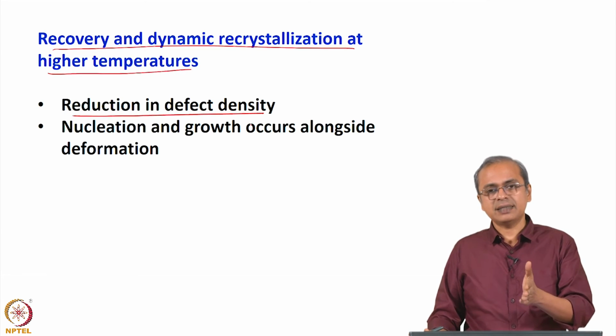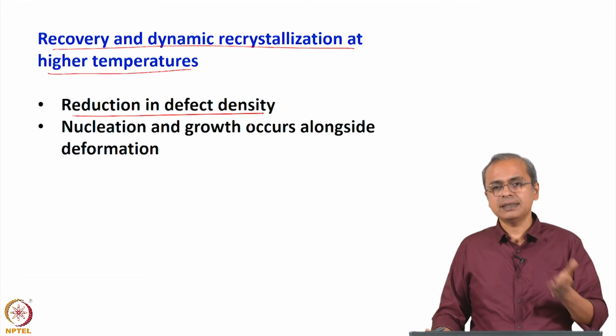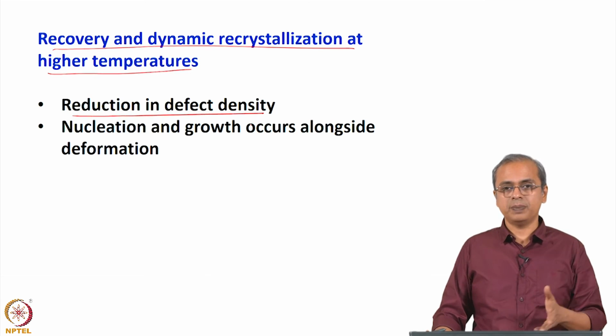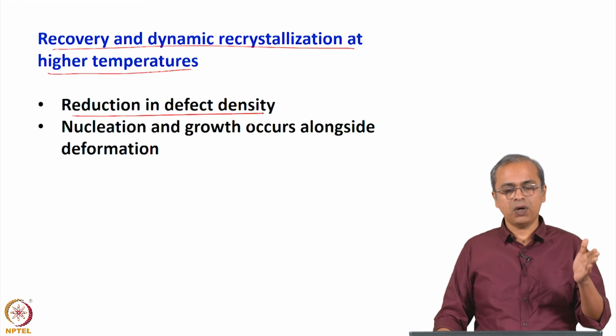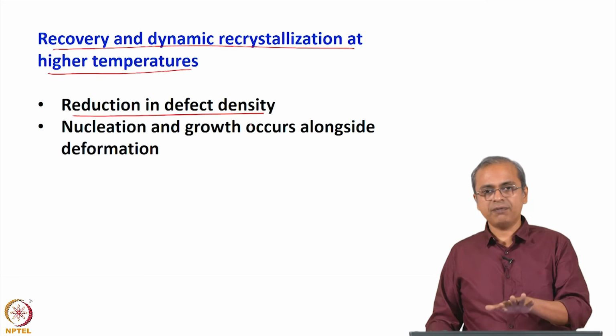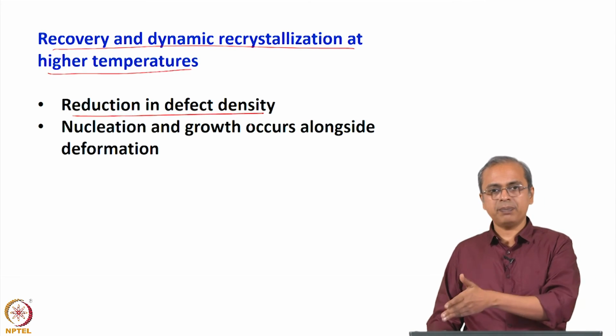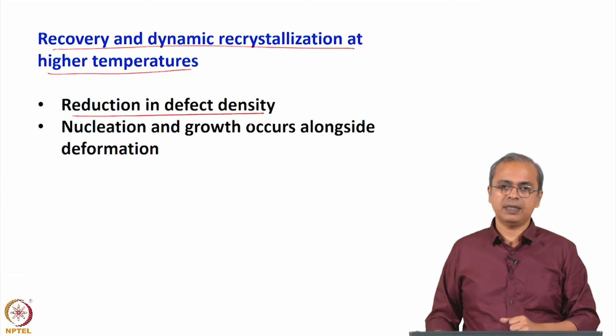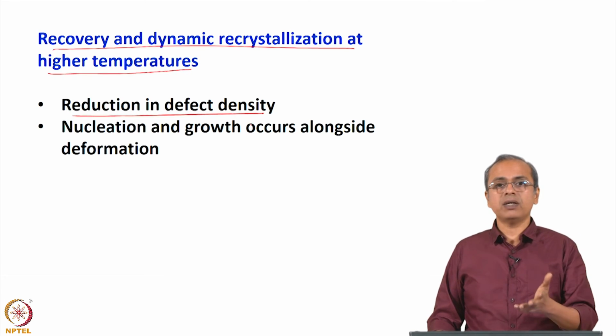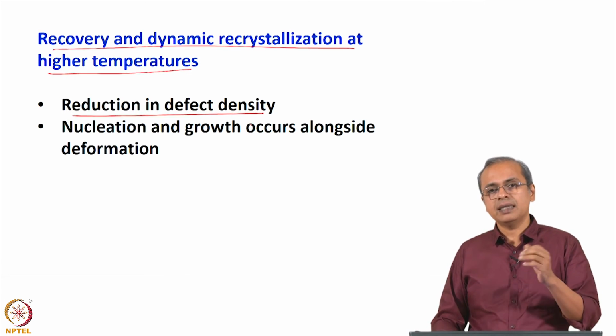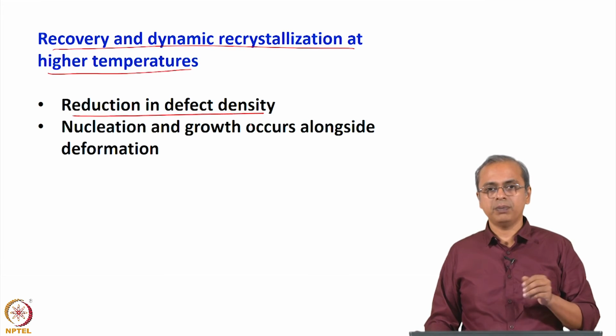And in an industrial setting, that is not a nice thing to have, because you are wasting energy. If you have done, say, 5% deformation with some amount of energy, it would be nice to do the next 5% of deformation also with the same amount of energy. If suddenly the energy requirement is going up significantly, then your cost for doing the deformation goes up.